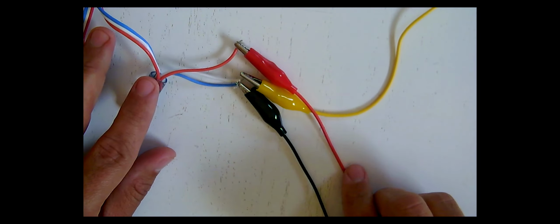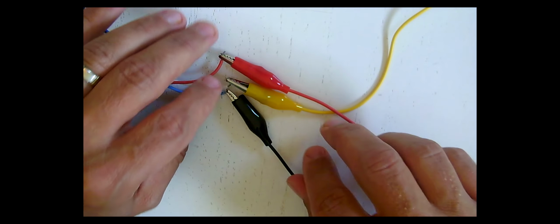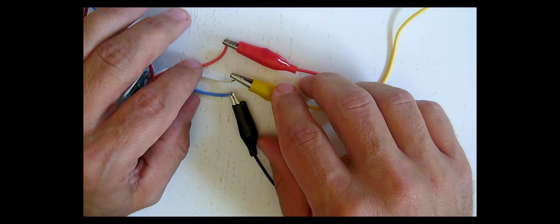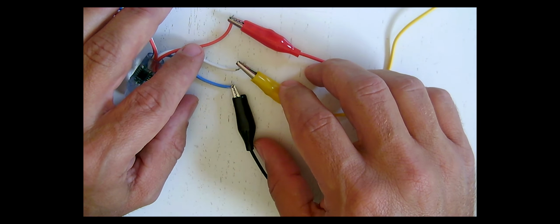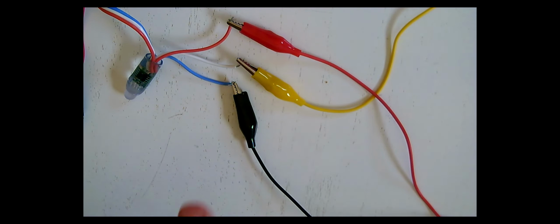this is one of the LED light bulbs, and you see the wires coming off of here. And we do want to keep these separate so we don't get a short, but this is the other end of the 3 cables. And it might not be immediately clear, but the red goes to red as usual, providing the power, and the black goes to the blue wire coming off of the light bulb in this case. And then the yellow is the signal cable, just like it was in the servo example.